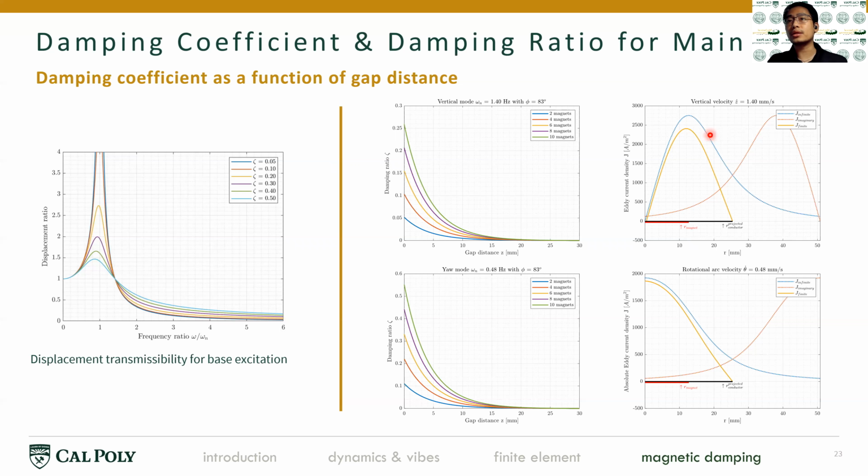We need the current density to go to 0 at the edge of the projected conductor, or at the edge of the copper stage, because otherwise you don't have the current outside of it. So you need to subtract the imaginary current density outside of the so-called infinite current density to get the finite current density. And this is shown here in the plot, where the yellow curve actually ends at 0. So make sure that our animation has the correct data points.